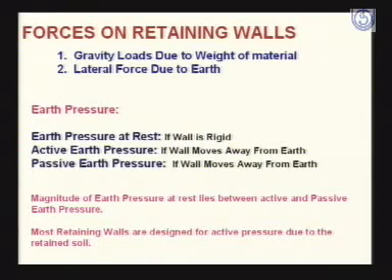So if we see this gravity loading of that material retained, then this is not going to pose any serious problem as far as the stability of the retaining wall is concerned. But this second type of force, this lateral force, this is really the major villain as far as the stability of the retaining wall is concerned.